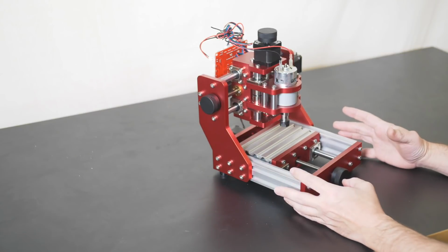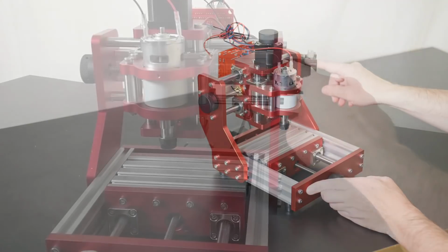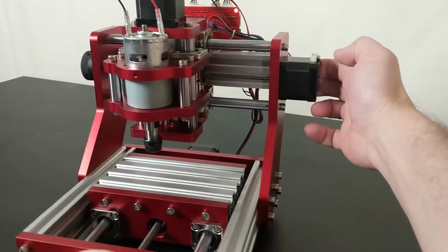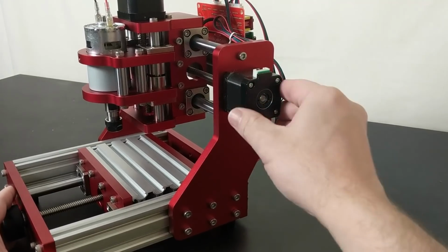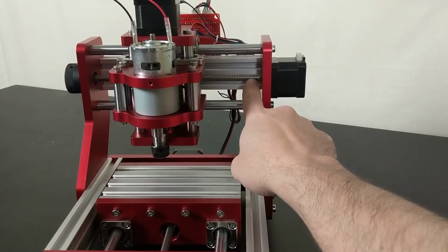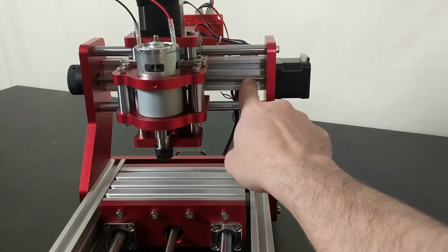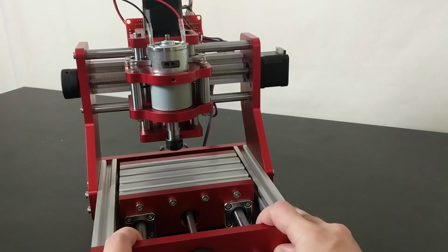First of all, I love the red anodized colors on all of the plates. Awesome. The lead screws are integrated into the stepper motor, so that's glued into the armature inside the motor there. So that's just a very nice connection that doesn't require either a rigid connection or a flexible connection, as we typically see with stepper motors on like 3D printers.